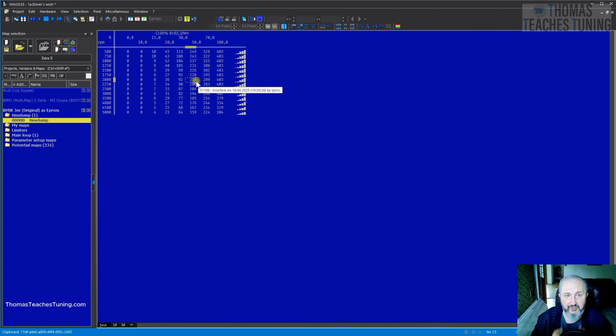So now let's return to the characteristic I was working on. Here are marked which parameter will be sent further. At the moment, if the driver presses 50% of the accelerator pedal and the engine speed is 2000 rpm, it corresponds to 215 Newton meters. You might wonder what happens if the driver presses 40% of the accelerator pedal. We do not have that value at the axis. Would there be an interpolation between these two numbers? Yeah, this is how it works.